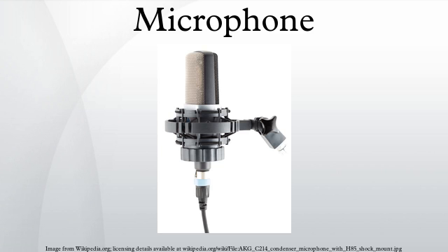Microphone polar patterns, microphone facing top of page and diagram, parallel to page. A microphone's directionality or polar pattern indicates how sensitive it is to sounds arriving at different angles about its central axis. The polar patterns illustrated above represent the locus of points that produce the same signal level output in the microphone if a given sound pressure level is generated from that point. How the physical body of the microphone is oriented relative to the diagrams depends on the microphone design.